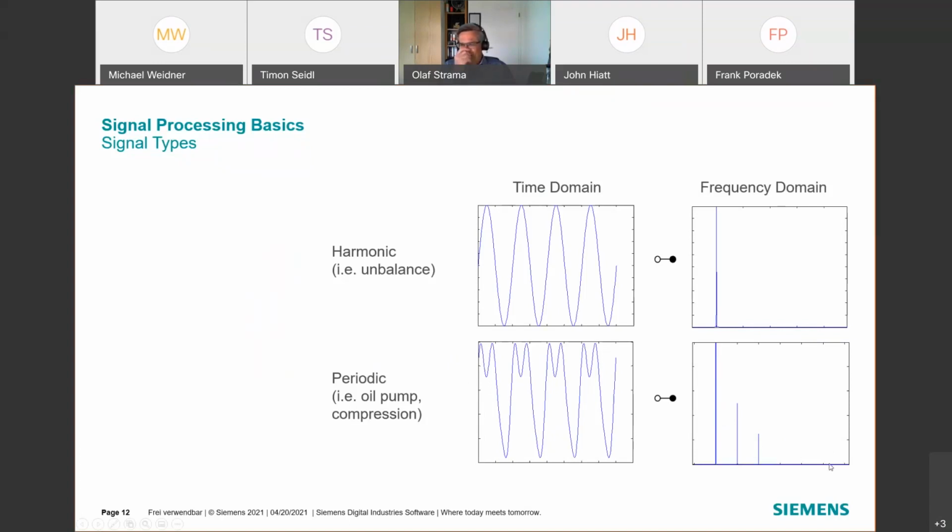So if you look at the spectrum, for example, it could also be an order spectrum, and you see one certain line, then you should have a look at the frequency that is twice the frequency of the line or 3 times the frequency of the line. And if you also see a contribution there, with a high probability these lines have only one origin, which is a periodic signal. This could be, as I already mentioned, an oil pump that we see on several orders with some harmonics.